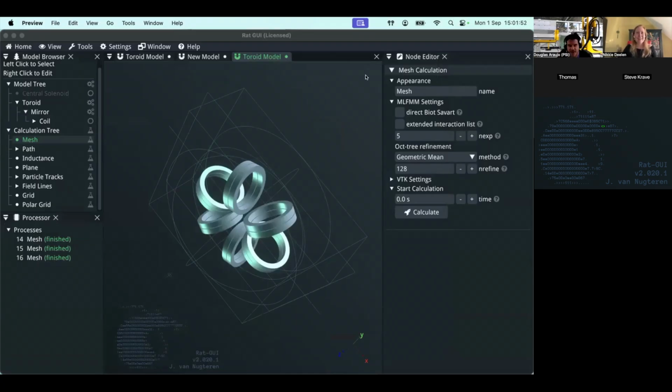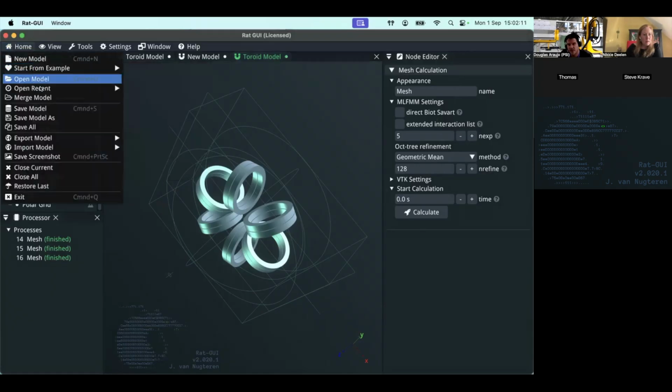I do have a question, Nikki. So if we do the model of the coil and then we want to run mechanics, when we do the export of, let's say, the force density, do we also have the coordinates of the 4 or 8 or more nodes representing the element that was used to compute the magnetic field?